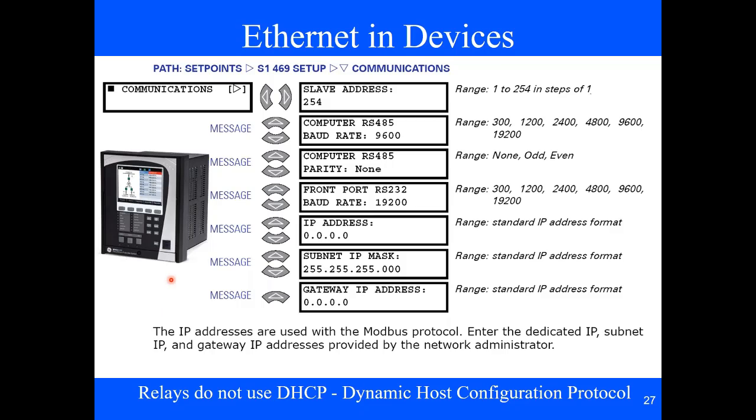Recently, I saw a presentation by Siemens on a device, and they can actually give their devices, and Danfoss drives can actually do this too, where you could have the PLC assign a DHCP address. And they do that by knowing the MAC addresses and some other factors. So that's what it actually is. If you want to connect to a device, especially if you're talking serial, you're going to need to know the baud rate, and you're going to have to know the slave address, or the IP address.